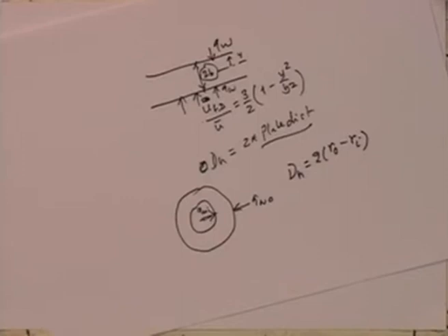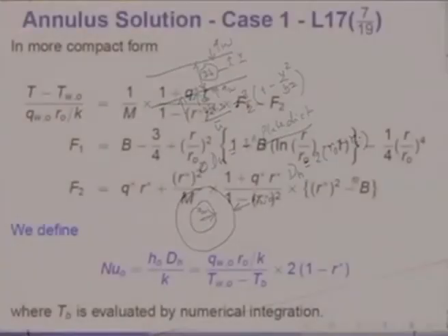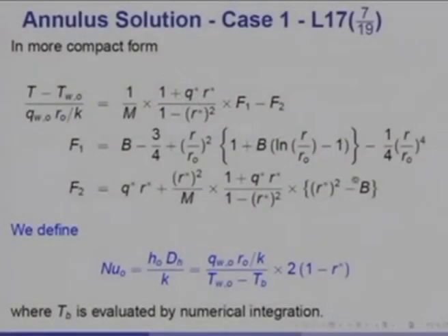So, with this temperature now, you must evaluate the bulk temperature. Mind you, the bulk temperature evaluation becomes extremely difficult because there are logarithmic terms involved, and numerical integration is the best way out. It does not require too much effort.